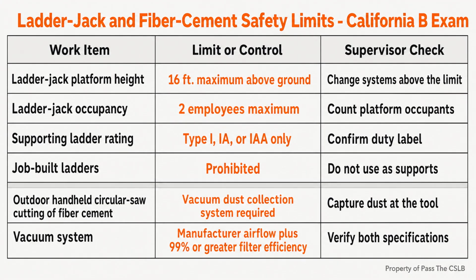Then I verify that the face connection follows the selected product's approved installation method. At joints and terminations, I do not borrow an expansion gap from another material. I verify the product instructions, plans, and applicable code. That is especially important at butt joints, corners, channels, windows, doors, and trim, where several systems meet.